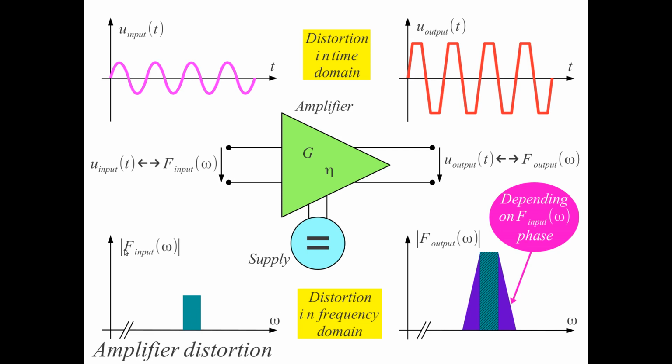In fact, for some transmitters where the spectrum is well defined, like UMTS base stations, we drive the power amplifier with the well-defined UMTS signal and look at the spectral regrowth up here. But this is a very uncommon case. Usually we have to find a different way to specify the input signal to actually observe the response of the amplifier, and we are going to look further at this in this hour. So how to define this?